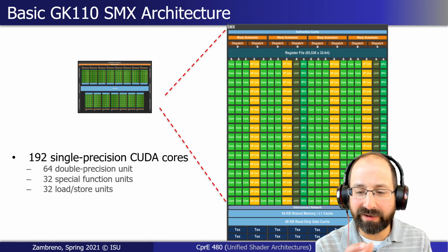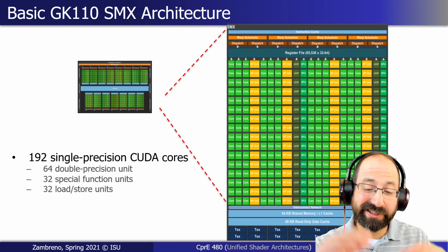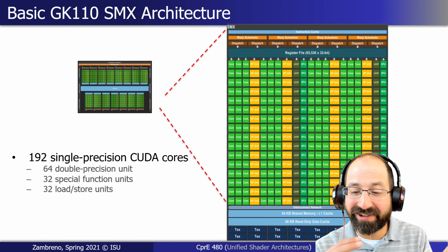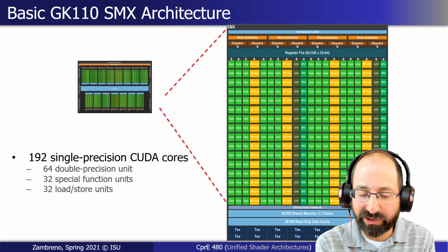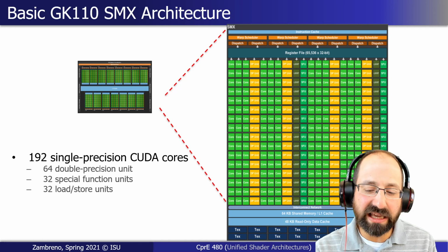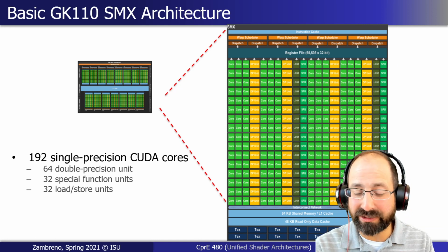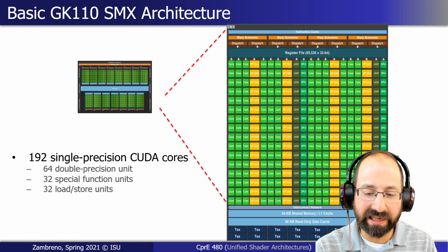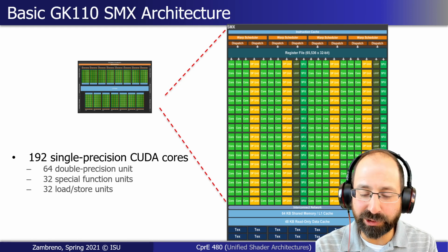So you don't have to worry about going from Q16.16 to Q32.32 and then truncating back down. There's some real value and advantage of simplicity of data layout for single precision hardware. But each of those individual units, and we're talking about the adders here, not to even start with the multipliers and the dividers, are so much more significantly complicated than the equivalent integer hardware.